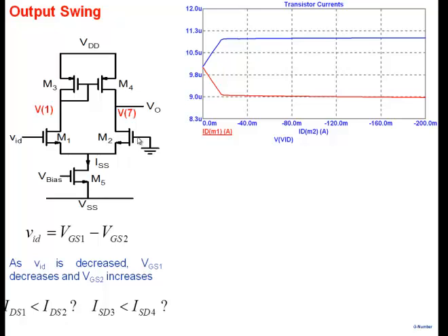Then how do you explain this? First order, what do you think will happen? If current switching doesn't occur, if current remains the same 10 microamperes, then VGS1 of this should remain constant. Agreed? So if initially this is minus 1.5, and I make it minus 1, this will become minus 2.5, VGS remains the same. Fine. So current is the same, no problem. But then VGS here has increased so much.